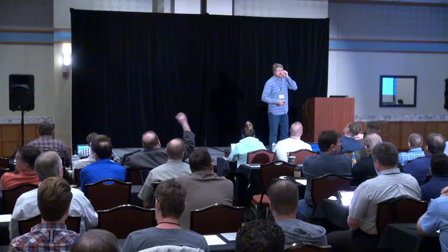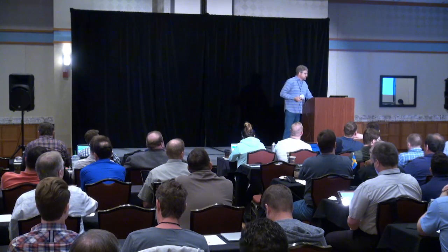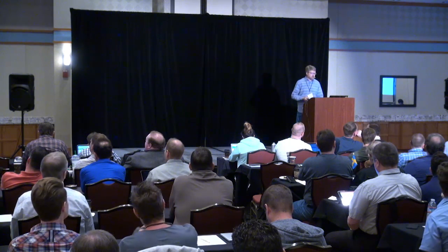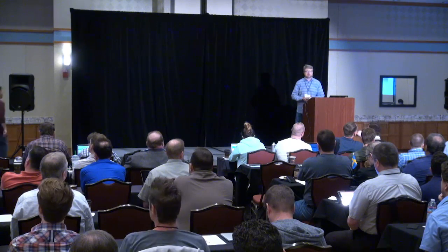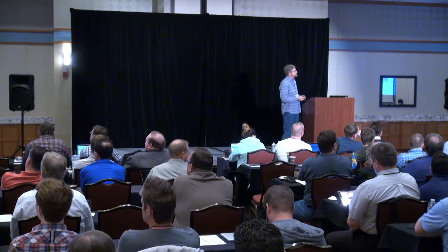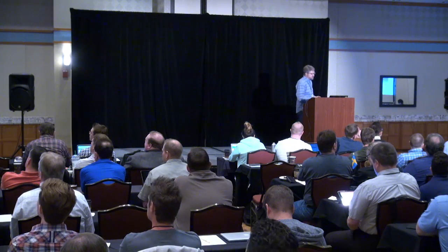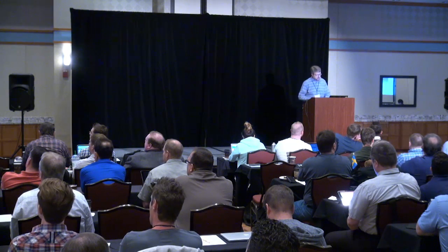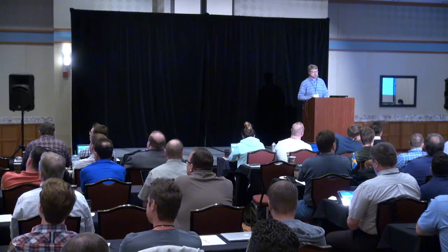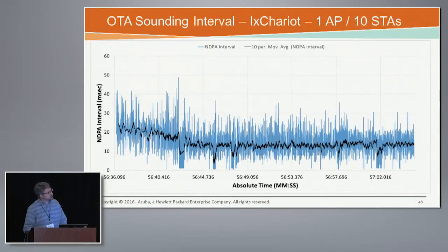Is it dependent? Yeah. If we found that it's dependent on the number of stations, the answer is absolutely yes. So here's 10 stations with a moving average. So you see the jitter, right? There's a lot more jitter. Here the jitter was about 8 milliseconds, so here it's significantly higher. So this is a 10-station test. Now the moving average is around 15 milliseconds after we get through the training interval. So significant acceleration of sounding.